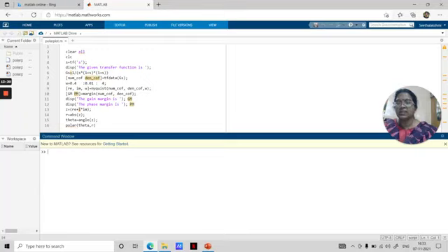Now we have to assign the various values of omega. So the starting value I have assigned is 0.4 and the step value is 0.01, that is 0.4, 0.41, 0.42, like this. We are going to take the scale till 4. Okay. This command separates the real part and imaginary part of this transfer function for various values of omega. So for the first value of omega, 0.4, it separates the real part and imaginary part. This command calculates the gain margin and phase margin of the given transfer function.